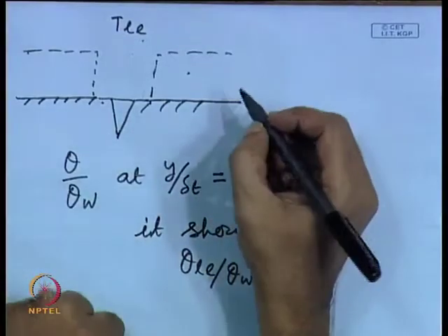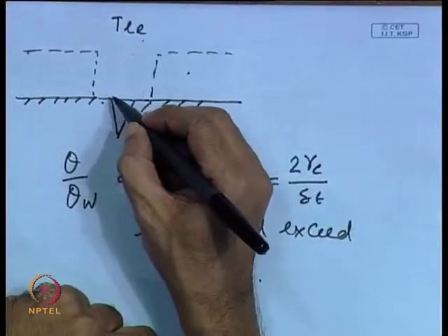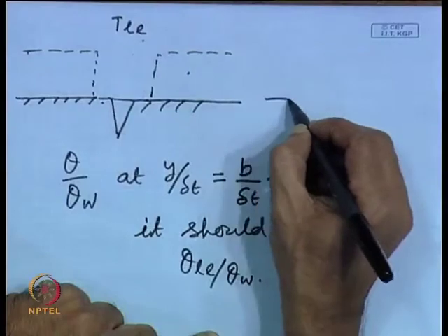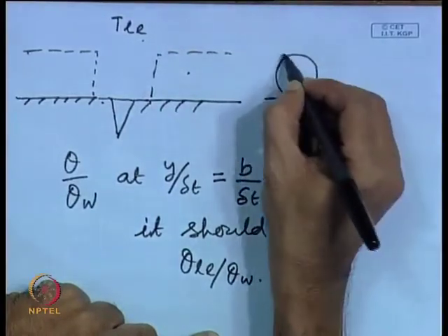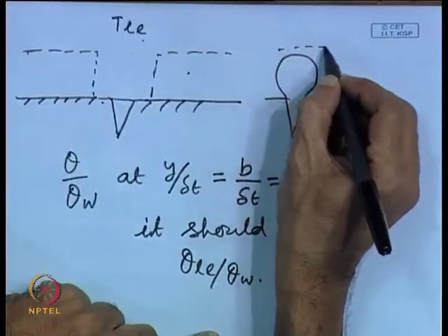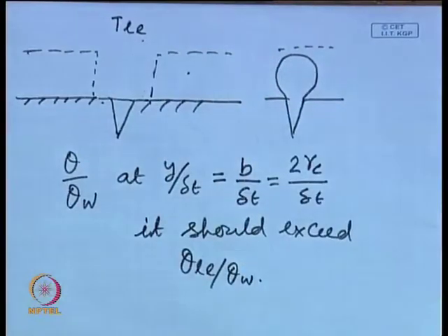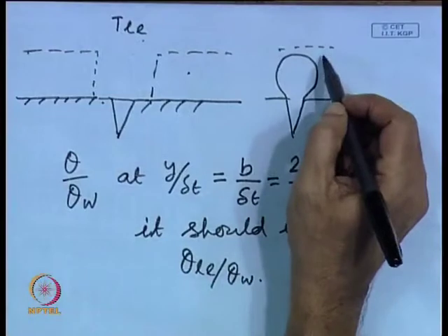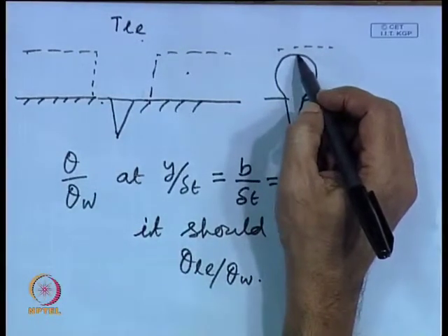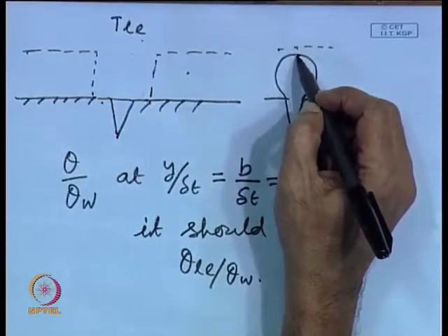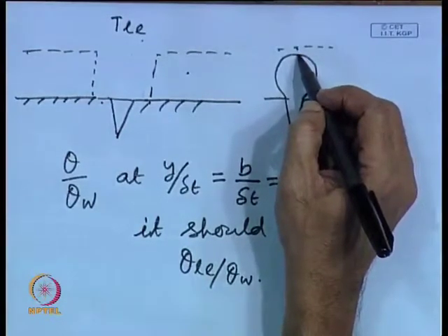That means, when the bubble embryo is growing, even the topmost portion of the bubble embryo is submerged within a high temperature liquid. So, the maximum point which can touch the edge of the thermal boundary layer is this.